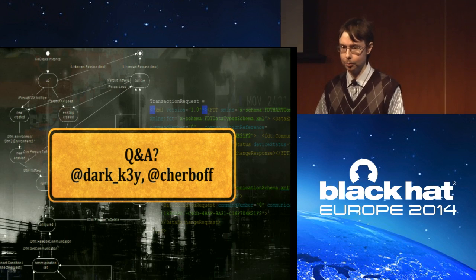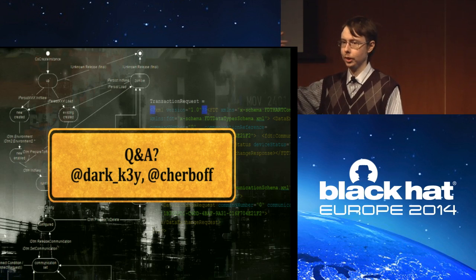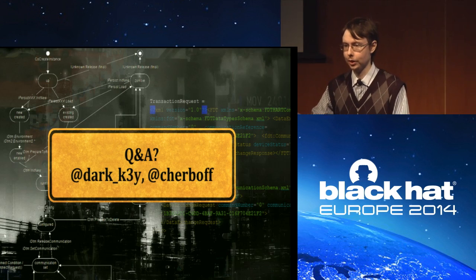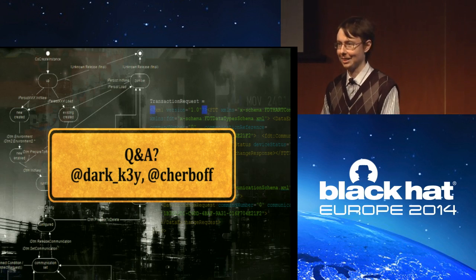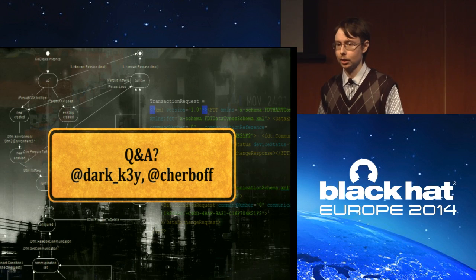For example, in iptables, when you have a current loop connected to the field bus and the field bus connected to the Ethernet, you could put your server with iptables between the plant asset management and the Ethernet field bus gateway, for example. It's a cheap solution. It's a free solution. And directly write the signatures with deep packet inspection and deny such packets, just based on the exact vulnerabilities.